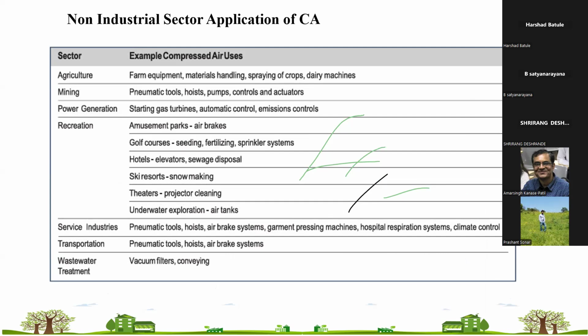Okay. Blowers, root blowers are used in agitation, wherever there is cleaning or clarity of water has to be there. So these root blowers are continuously used in wastewater treatment. That will be compressed air, but it is an application of compressor. Root blowers are a type of compressor, whichever has a low pressure, but more than your ambient pressure. Yes.